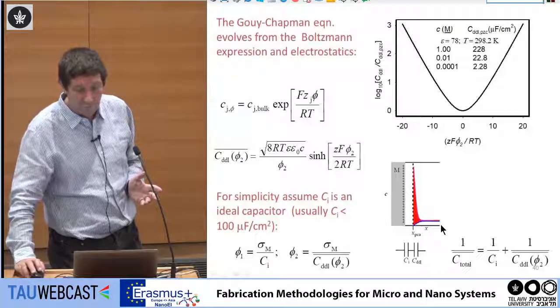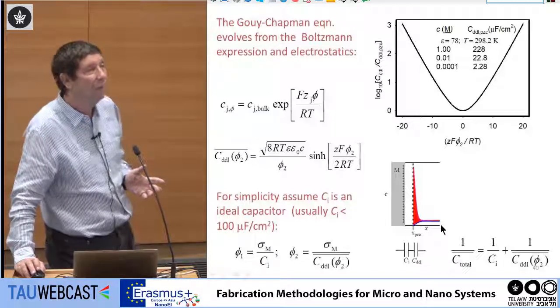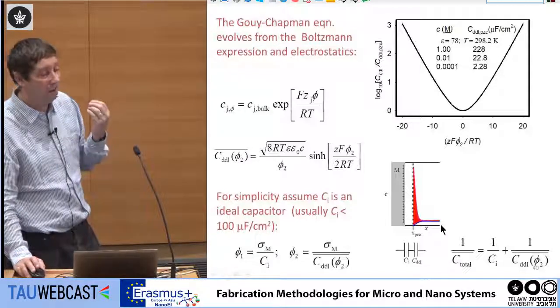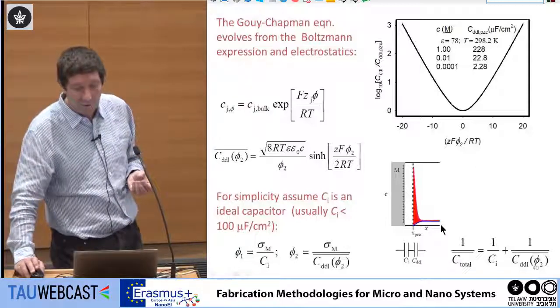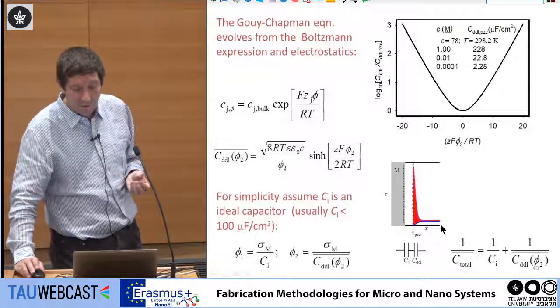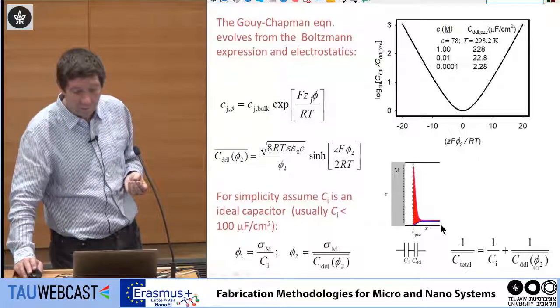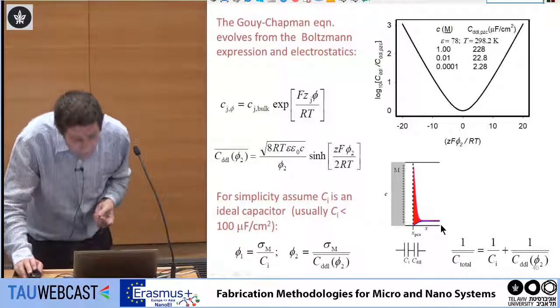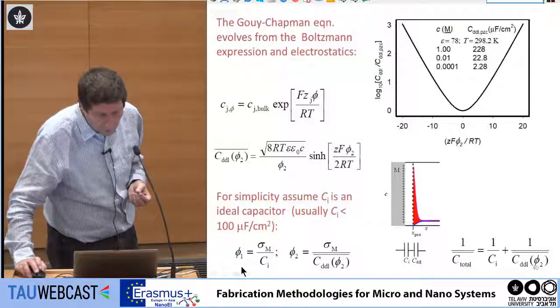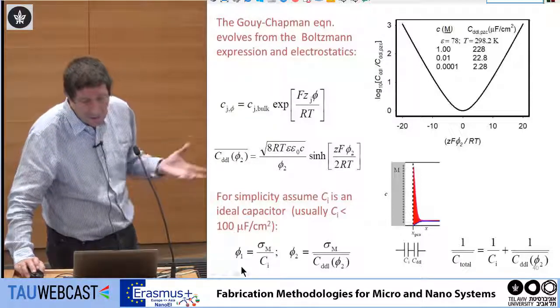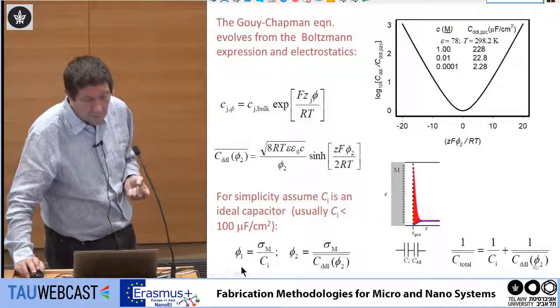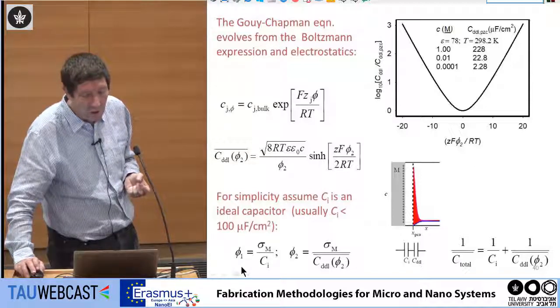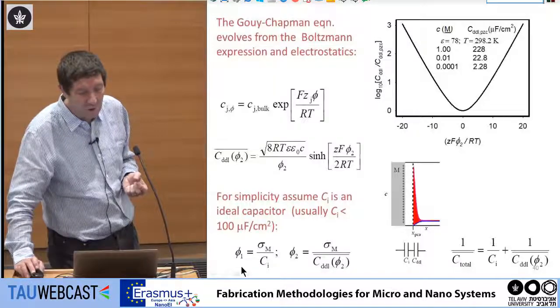So if you look at the model of an electrode touching an electrolyte, you have two capacitors. The capacitor of the double layer of the inner Helmholtz plane, we call it, I put here Ci, which from electrostatic theory is the charge divided by the potential Phi; the potential times the capacitance Ci is the number of charges.